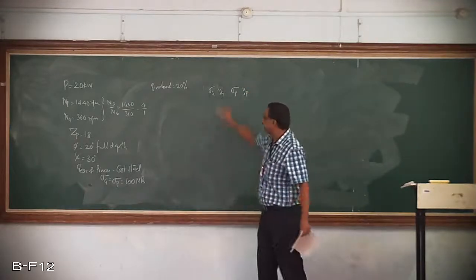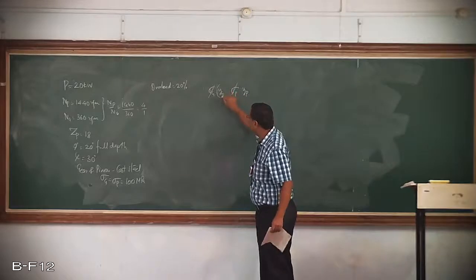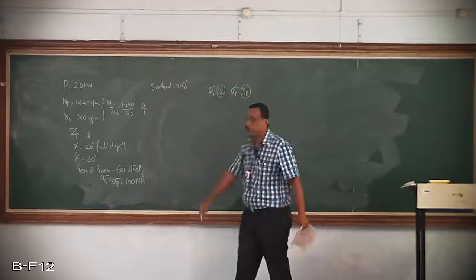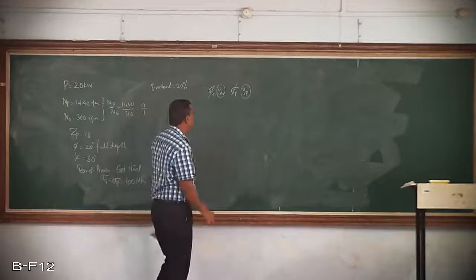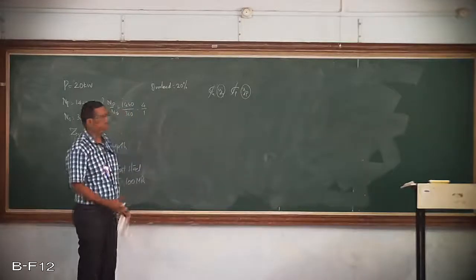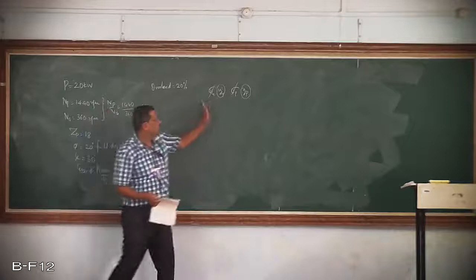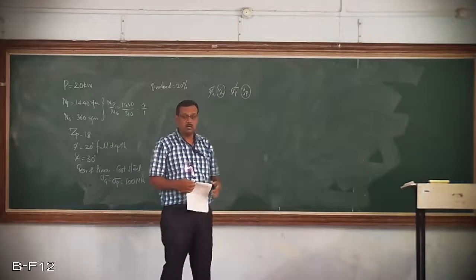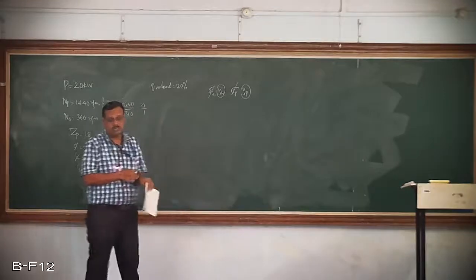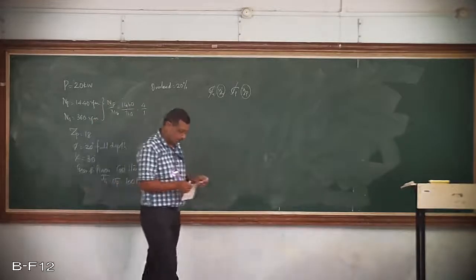Now, when both the materials are same, it depends only upon the form factors yg and yp. As already seen in spur gears, when both the materials are same, naturally the pinion will be the weaker member compared to the gear. Therefore, we have to design for the pinion.